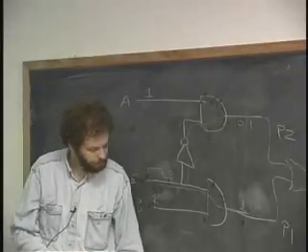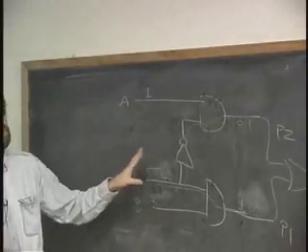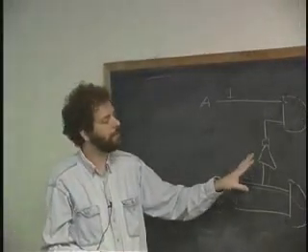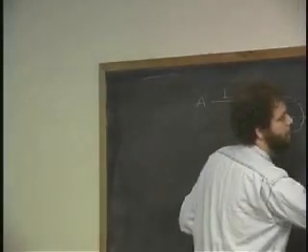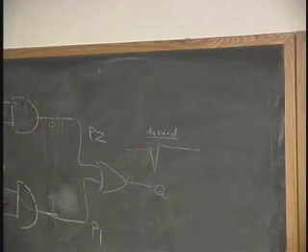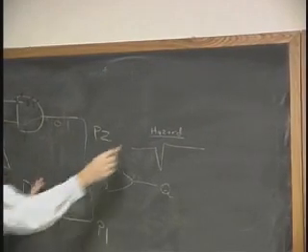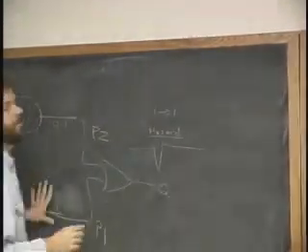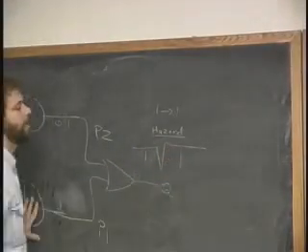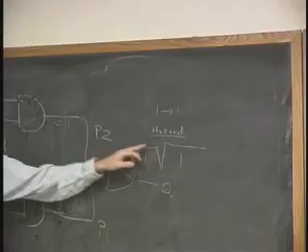And in general, computers inside are filled with problems like this. The technical term for this is actually, it's called a hazard, okay? Like a road hazard, okay? And in particular, this kind of hazard is called a 1-1 hazard, meaning that we started out with an output at 1, and we ended up with an output of 1, and we generated a hazard.